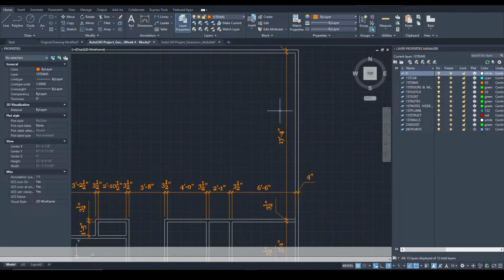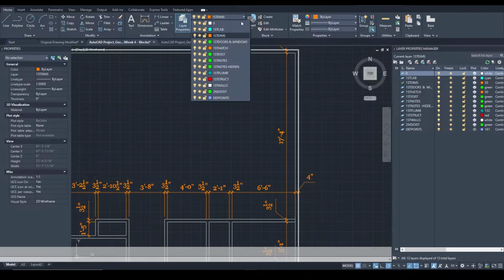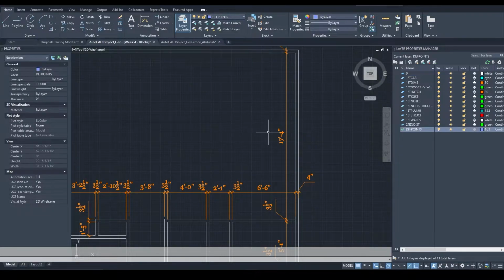And the best way for you to try to keep in line with all the walls that you're creating is to create a reference line. Essentially what that would be is an infinite line that is going to work as a reference. The best layer to do it on is the layer that is not going to have anything printed on it, which would be the def points layer, which you have by now. Go ahead and click on